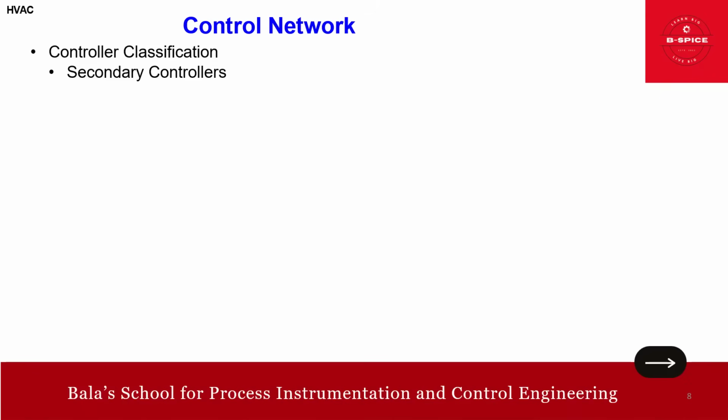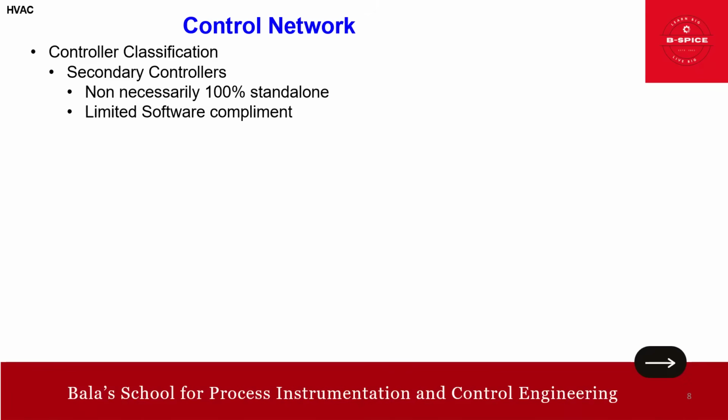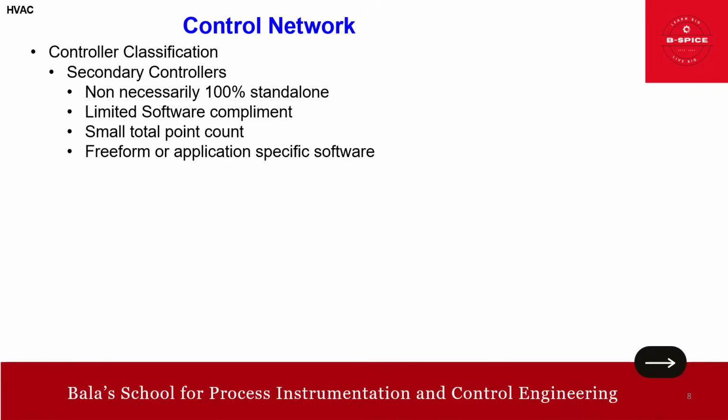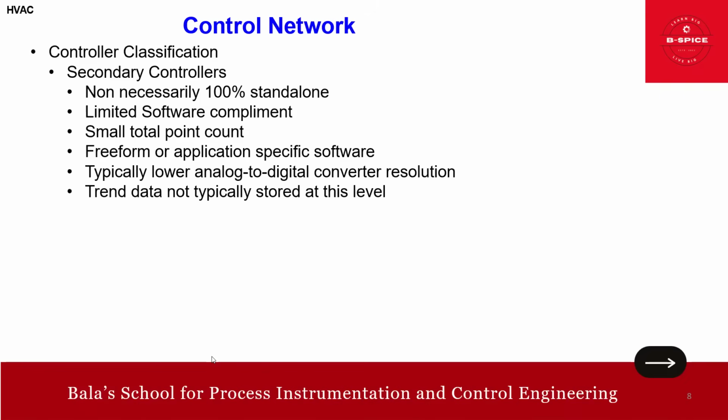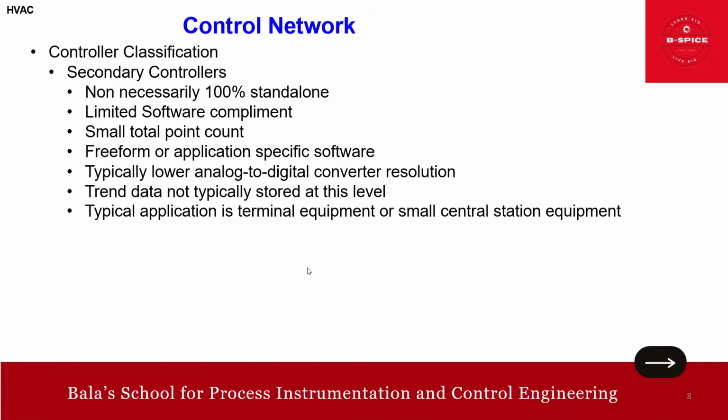Okay. So when we talk about the features: not necessarily 100% standalone, limited software complement, smaller total point count, limited free-form application software, and typically lower analog to digital converter resolution. Trend data is not typically stored at this level. Typical application is terminal equipment or small central station equipment. So that is about the secondary controller, friends.